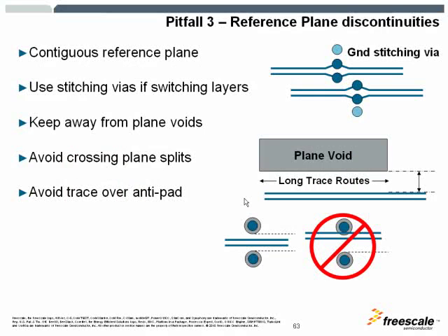The other pitfall would be that you should make sure to avoid cross-plane splits, and make sure you avoid traces running over each other's signals from the different levels.